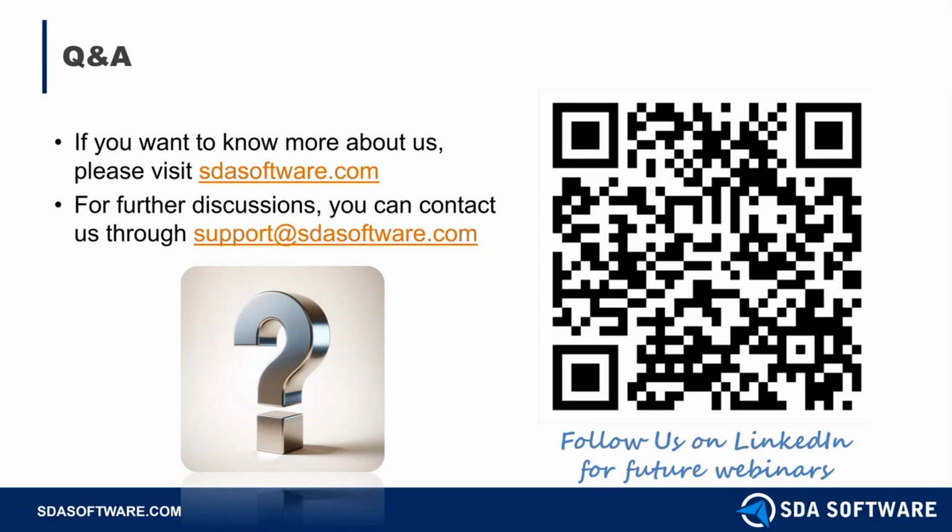And frankly, this whole validation is actually building up to a future webinar on transonic. So we can build on top of the processes and practices, and then better translate them into the transonic and supersonic regimes, so it can span wider later in the future as well. But yes, you could use segregated flow for low subsonic, but in our testing the difference is minimal, and we can keep a more consistent CFD process and practices. That's why we keep it in the coupled flow solver.